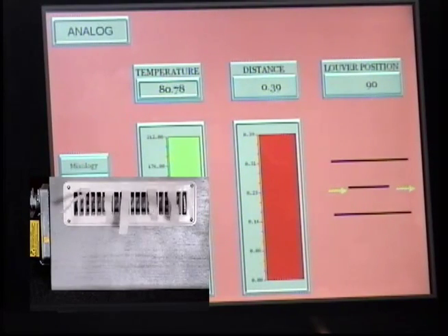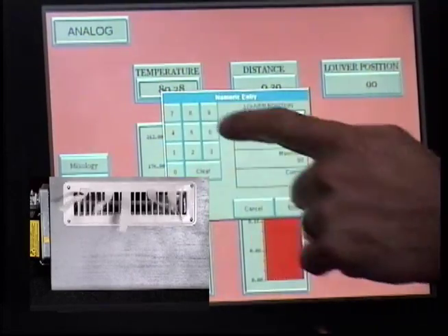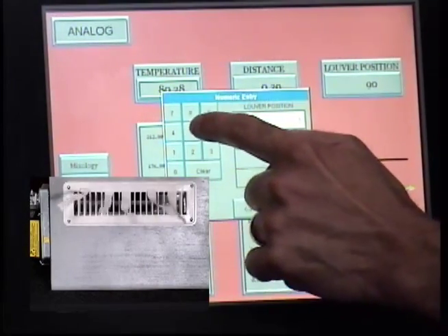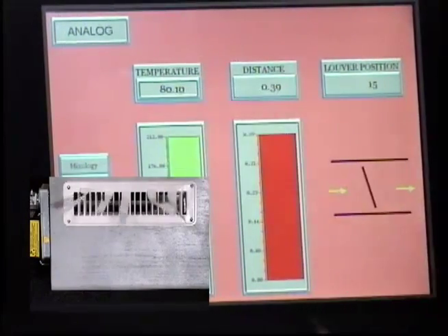Shane just changed it so it's full open, and you probably can't hear or see it, but the actual damper motor there on the side is controlling the register vent in there. And if you want to, you can close it all the way down, and we can see we effectively shut off the airflow. I'm going to do 15%. Okay, we'll cut down the volume.